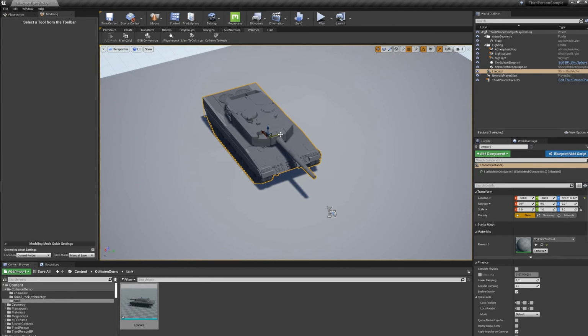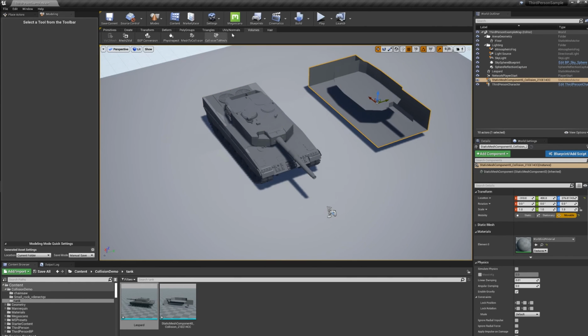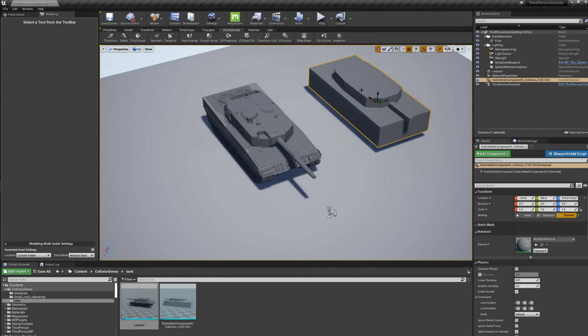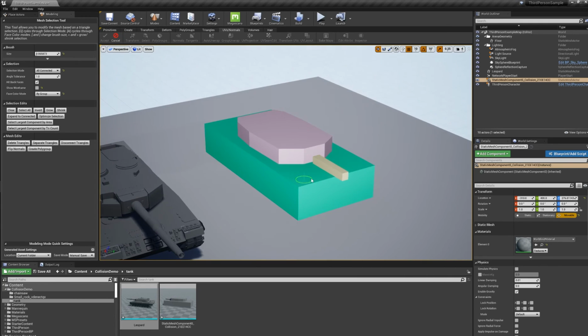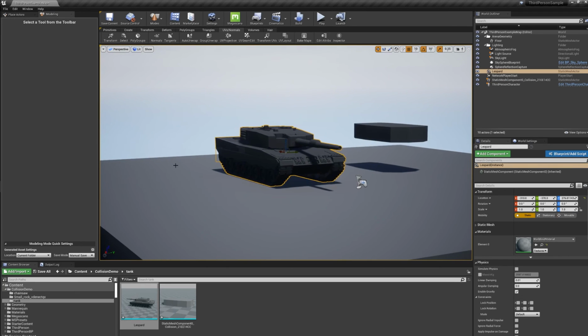And then I'm going to do collision to mesh. Drag that over here. You see it flip the normals. We'll go back. We'll fix the normals. And then I'm going to jump in the select tool and I'm going to say both of these are bad. Delete them. And there's a random piece back here, which was the next biggest piece because we have that minimum of 4. So that one's okay.